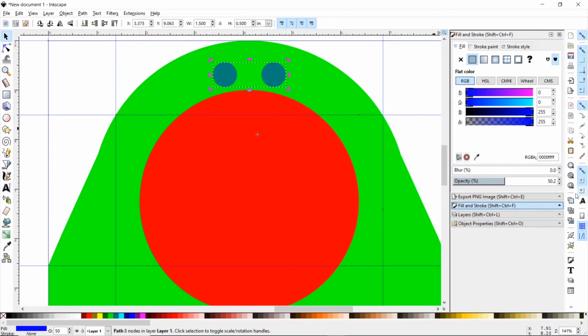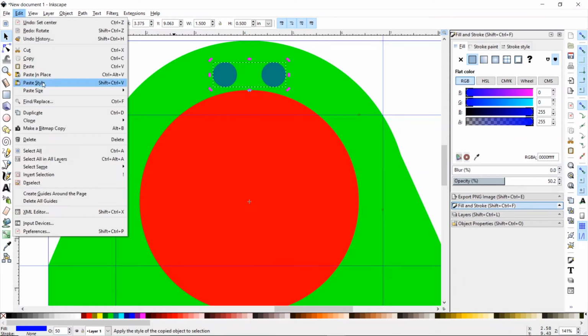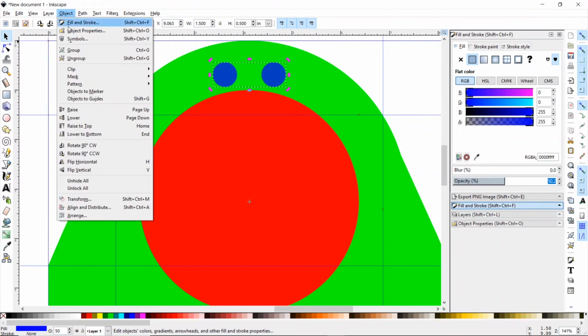This section right here is for snapping this stuff. There it goes. Now it's snapped to the center of this big circle. Now, if I do the rotation, it rotates it around this center point right here. So it makes it really easy. Alright, let's put those back to our starting point. I'm going to create 4 more sets of these, and I'm going to rotate each one to wherever we need to. So let's go duplicate, object,